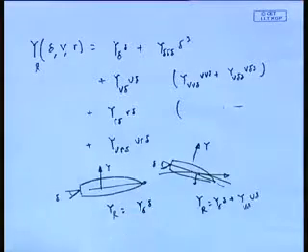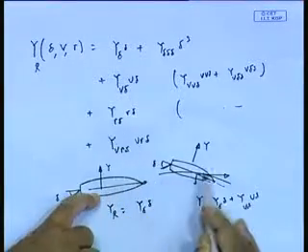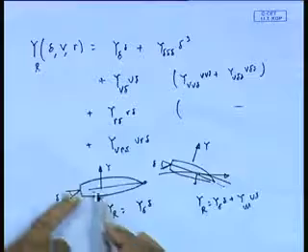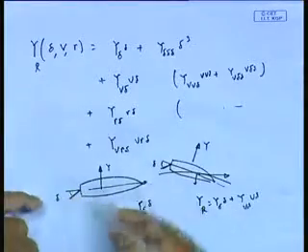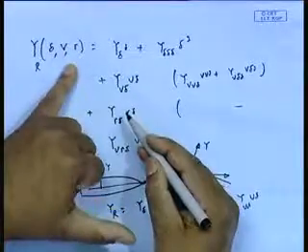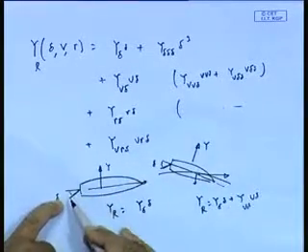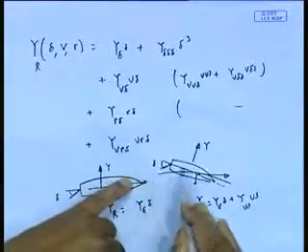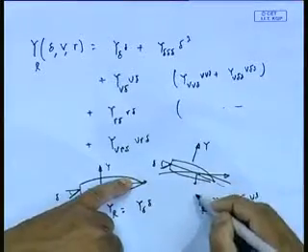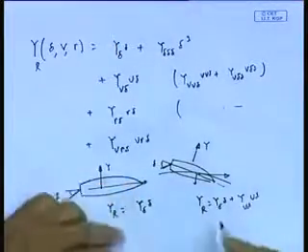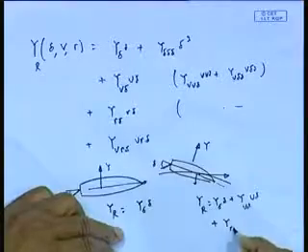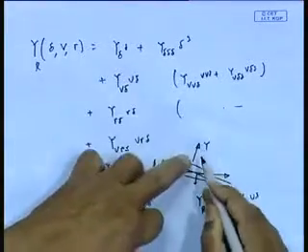What I am trying to say is that the force here and the force there may be different. Why? Because here I am going on a straight line, so the flow comes in a certain direction and I get a y force. But here, with the same delta angle, say a 20-degree rudder, the ship is already on a turn and has a certain v and also a certain r. So y_r_delta, this force, is also different.